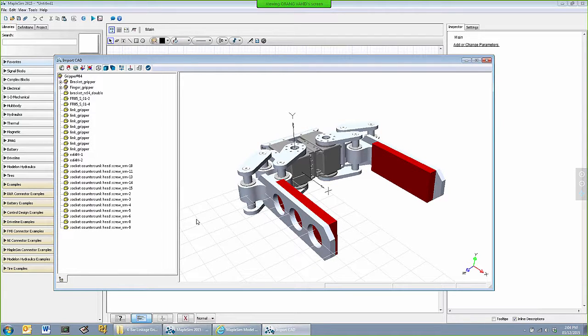It became apparent to us that the process of coming from a CAD design to a dynamic model in MapleSim would require an intermediate step where you need to arrange the model, potentially select components in it, and also group them. A detailed CAD model could have many small pieces in it, which will not contribute to a dynamic simulation aside from their mass and inertia. And there are things that you might just not want to model at the system level to begin with.